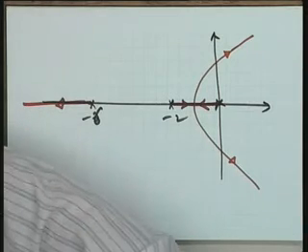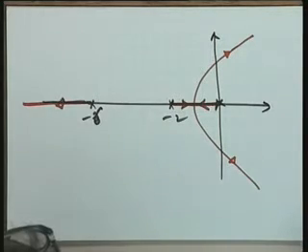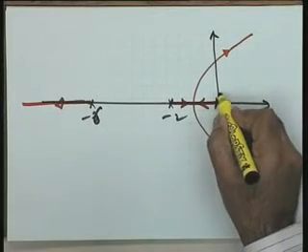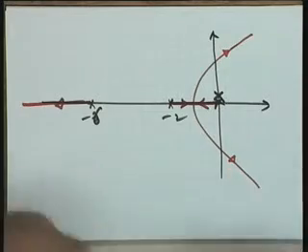Kv is infinite, steady state error is 0. You see, any specification you give, the steady state requirement is satisfied. If I place a pole at the origin, I do not have to worry about the steady state requirement at all.